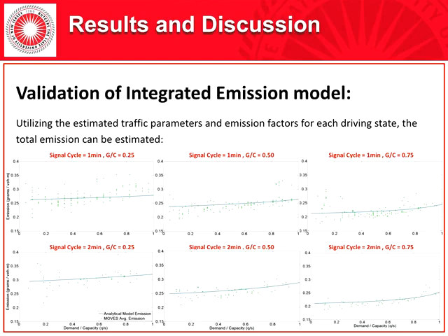In fact, the great value of this method is that it is based on aggregated traffic characteristics to provide aggregated emission estimation. We don't typically care about the emission from each individual vehicle. Instead, it's more important that we design streets and intersections to perform well as a system. Therefore, this model is a step toward improving our ability to assess total emission associated with the traffic in street networks.